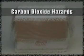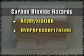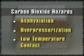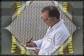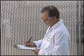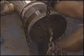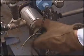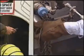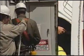Let's review the three basic hazards of using carbon dioxide. They are asphyxiation, overpressurization, and personal or material contact with carbon dioxide. Avoid asphyxiation by requiring work permits and confined space entry permits anywhere there's a confined entry. Isolate confined spaces from all piping except breathing air lines. Check the air in confined spaces before you enter.